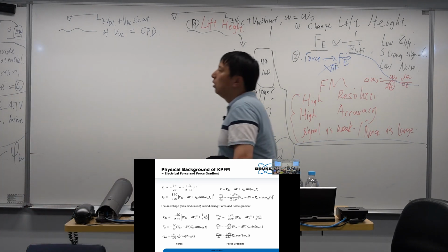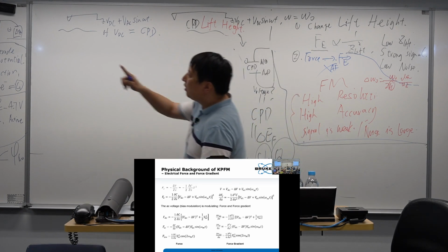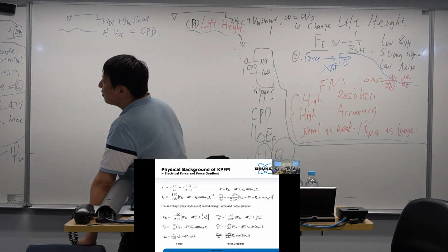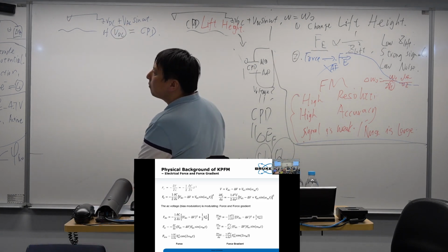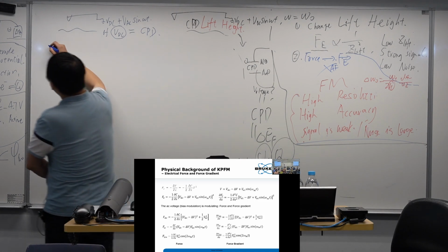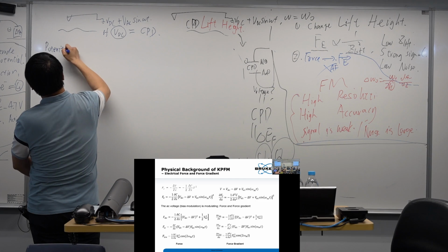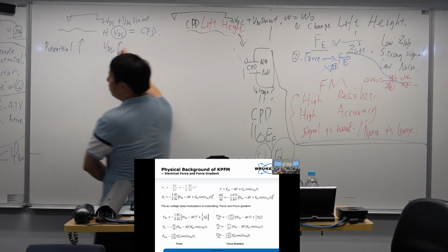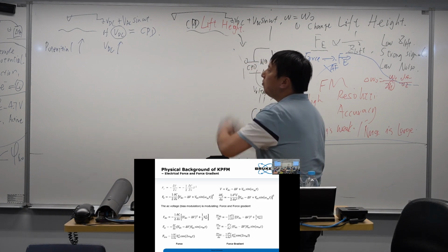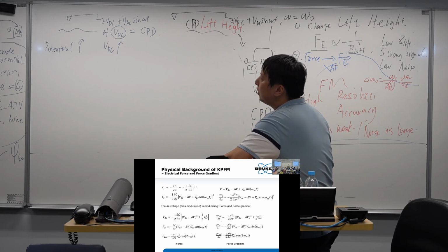When people look at this term, they found one thing. The detection of this method is limited by the range of the VDC. If the surface potential is large, the VDC should be large, because we need to compensate the potential difference.